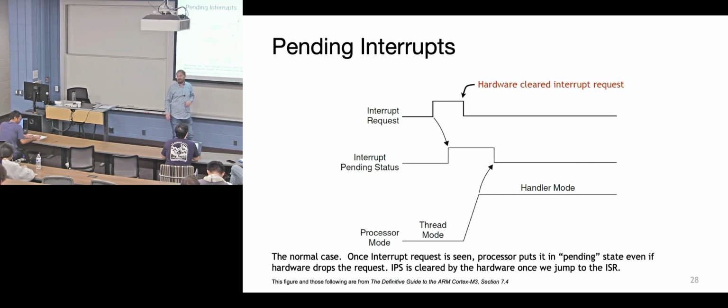Yeah. You're looking up the ISR in the vector table. Yep, that's exactly right. What else is happening? You're stacking the registers that you need to. Yep, so you're saving the state. First you've got to figure out where the interrupt handler is, so where's the code that's going to be run? That's the first part of the answer. The second part is you've got to save the state of your controller so that when you come back to your core, it's in the right state. That's the stacking. That's why there is some time delay here.